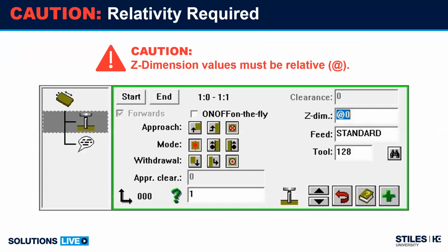The last thing we need to talk about is what do we do with the Z dimension? So when we're cutting with a straight up shear, down shear tool, we can tell the router motor where to cut in Z, -2 millimeters because we're on a vacuum pod machine. We want to cut 10 millimeters above Z, but we're not moving in the Z dimension. So the tool stays at that position.